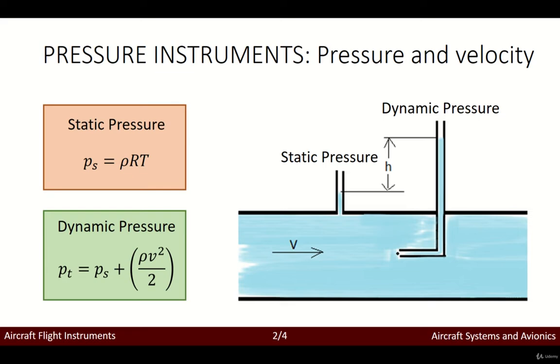static pressure. The dynamic pressure, however, is also related to the static pressure, but takes into account the velocity, the energy of a specific flow due to the fact that it has a certain velocity. So in aircraft you can easily perceive that the static pressure can be obtained, but also the dynamic pressure can be obtained, and it will be bigger because of the fact that we are moving at a certain speed. The aircraft is moving at a certain speed, okay? So the basic definition of static pressure we already took into account.